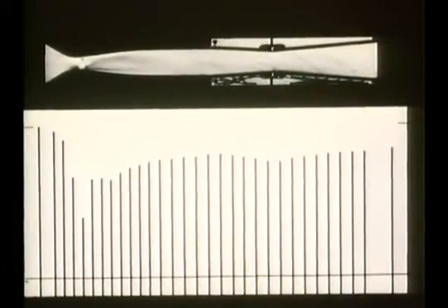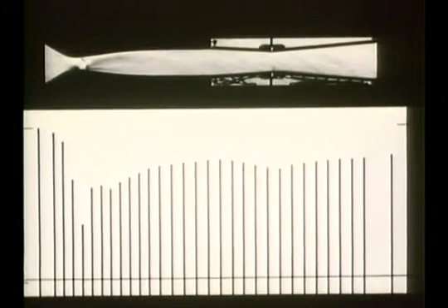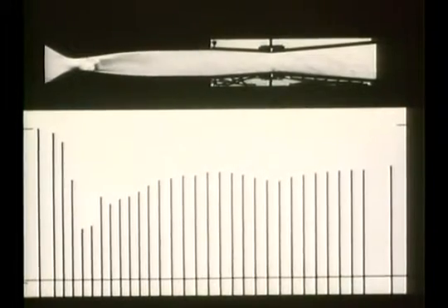To understand blocking, watch the shock wave moving downstream to higher Mach numbers. The dissipation in the shock wave is increasing, and the downstream stagnation pressure and density are decreasing.